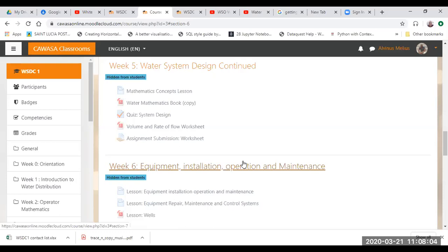In addition to that, tank maintenance is something we have to discuss as well, where the tank is emptied out, the inside of the tank is cleaned. Okay, we check to see if the coating on the inside, if it's a metal tank, the protective coating that protects it against corrosion, whether that is intact, and we make whatever repairs, and then we disinfect and put it back into operation. So stagnation should not be much of an issue with these tanks.